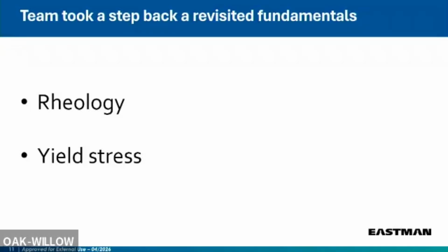Because we'll come to the analytical part of it, what progress we made from, you remember, the first trial where we had very bad sagging to the trial we showed you where the sagging had improved, was because of this. We are optimizing the rheology all the time. So once we realized that this rheological flow was very good for the high pressure of a lab application, but when it came to the Pro, it was not good enough. So the only thing we had to do was raise the thixotropy index, because that thixotropy index was good for particular application parameters, not for this application parameter. That was the hypothesis we used, and that is what we started with.